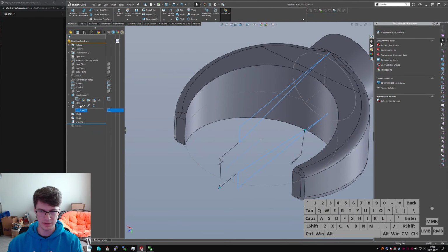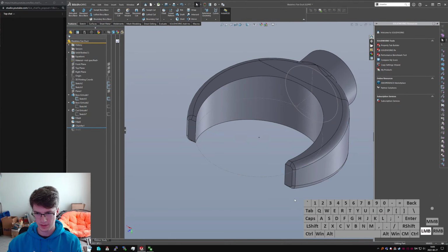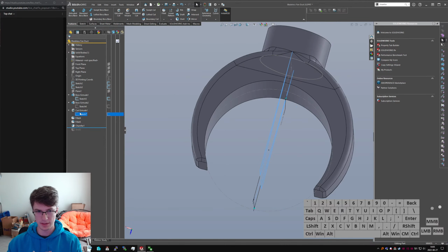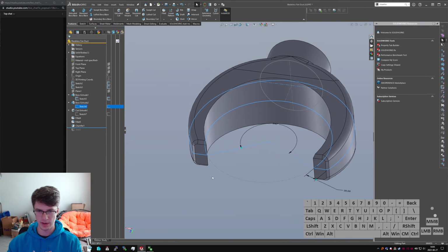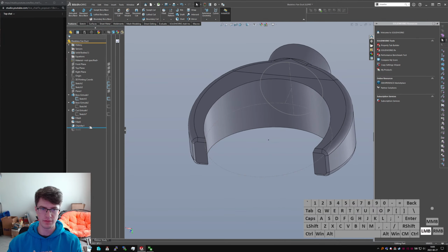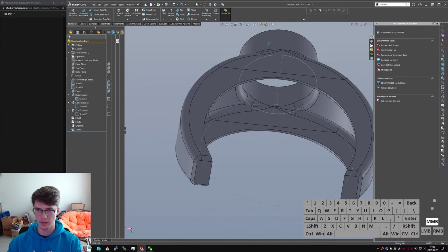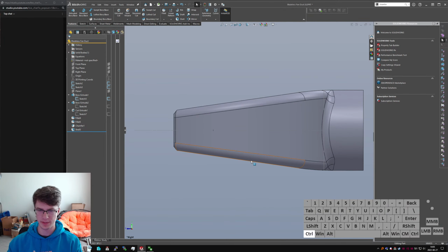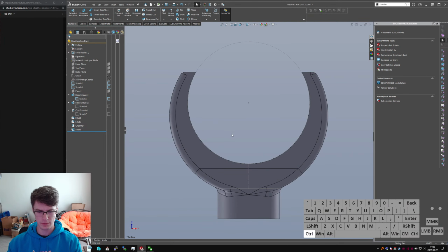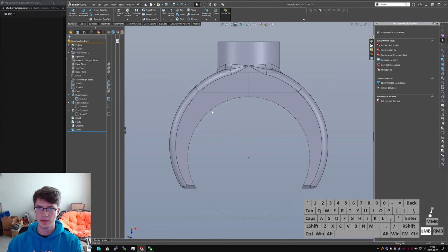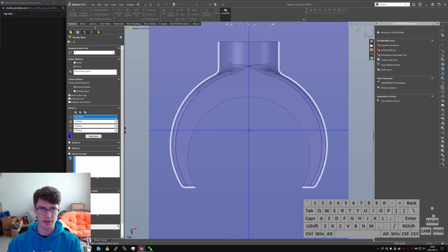Even though it does make things a little bit trickier to print, we can come back here and fix that by taking the minimum width of the duct up to 20 mils, and then we have way more printable area. I would have no fears about printing something this size. And even with the maximum overhang, which we can check by coming up top view. Yeah, top view. Just give that a quick slice in the top plane.